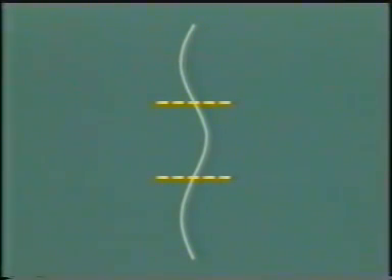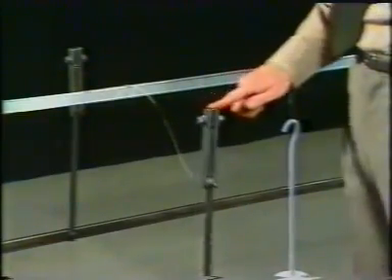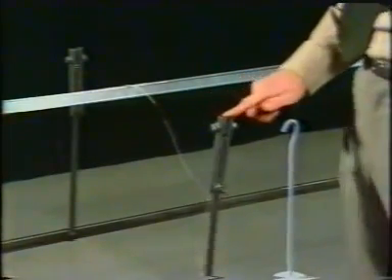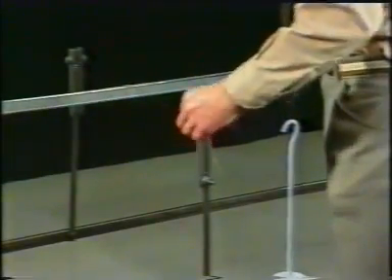In this example, although the bracing is very light, it has considerable axial stiffness. This stiffness is important. If the support for the bracing is less stiff, then, whilst the strength of the bracing remains the same, the effective restraint has been significantly reduced.